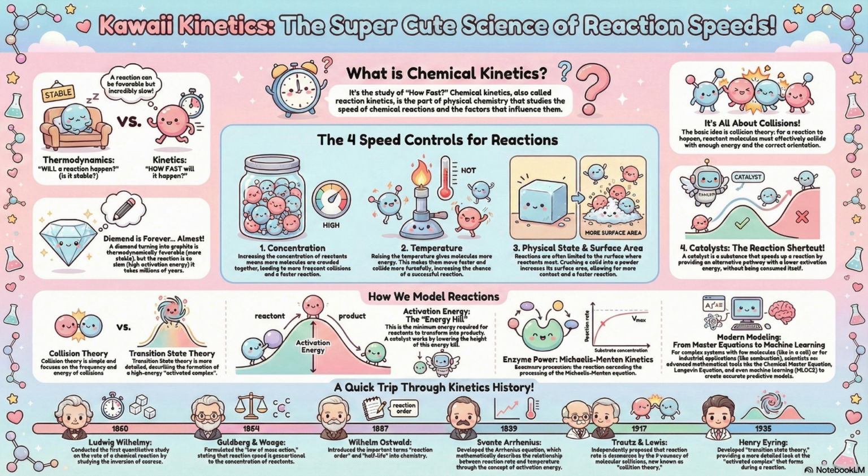It's a complete abstraction. The nodes and the reactions in the model don't represent real chemistry anymore. Instead, you have these virtual reaction rate constants. Just think of them as weights. And you tune those weights to get the right answer. You optimize them so that the simple model's overall behavior, like ignition delay time, matches the behavior of the full, complex, true model.